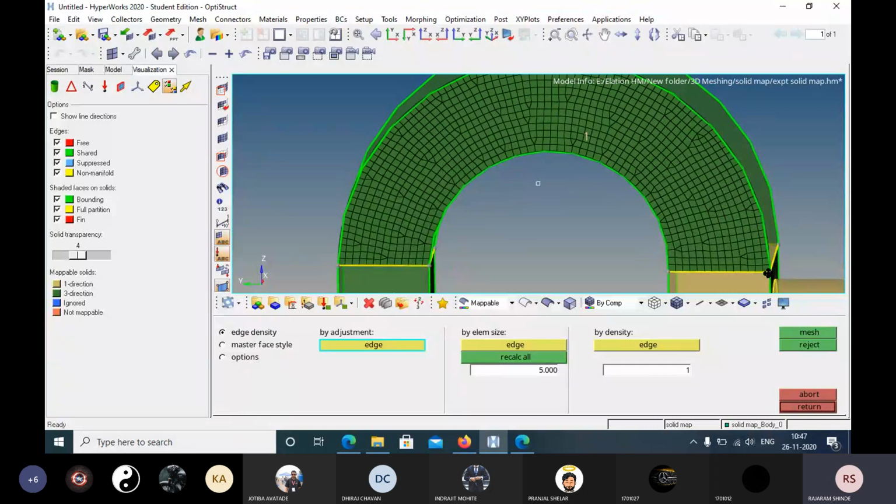See here, we can make 0 triangles. You can see here. You click on this line. I will click on this line. You will get one number here, 94. You click on this line. You will get a number here. You make an equal number of divisions of this line and this line. Okay. So I will enter here 75. I will set this edge. It will become 75. And again I will set this edge. It is also 75. Now on this side triangles are removed. Okay. Now maximum triangles are removed.